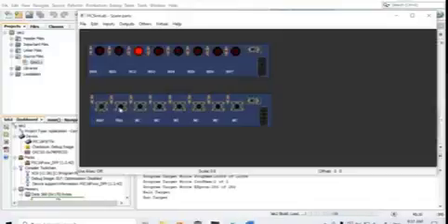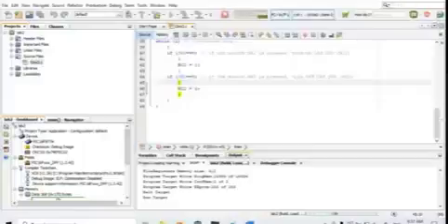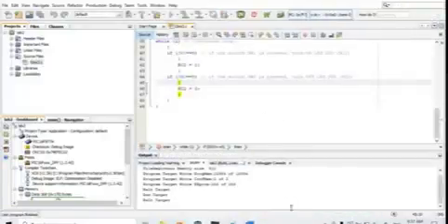Why? Because you need to observe back your coding. The condition only happens when switch RB0 is pressed, it will turn on. Other than that, if you press RB1, it will turn off. That one, we conclude the briefing for lab exercise number 2.